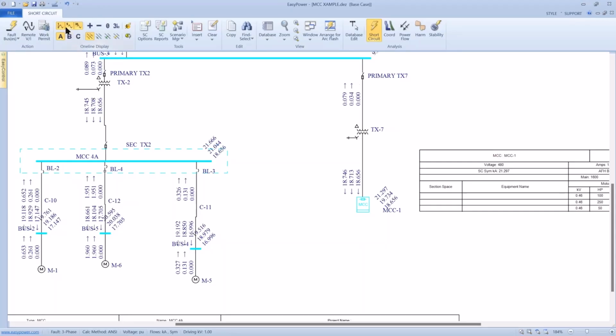If I compare the time slice between half cycle and 30 cycle, I see all my loads tabulate to 18,656, which is exactly what I have over here. So I have some difference in the way I've implemented the motors, or the way they're represented here, compared to what's going on inside the motor control center. For those purposes, I take some time to analyze or to understand. It's probably going to be in my impedances.